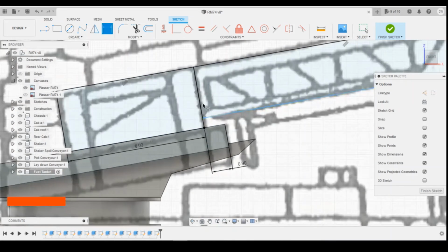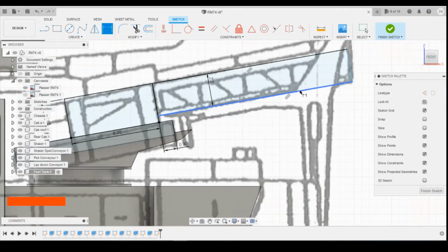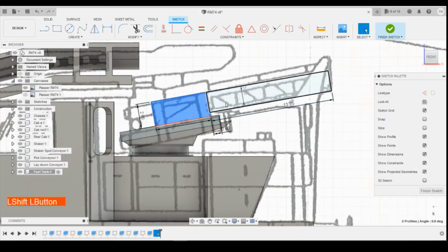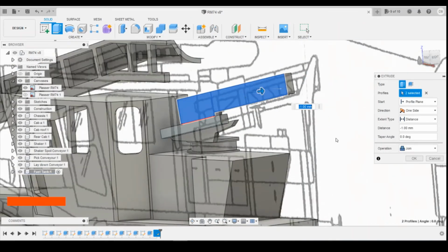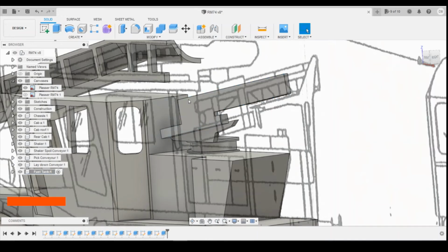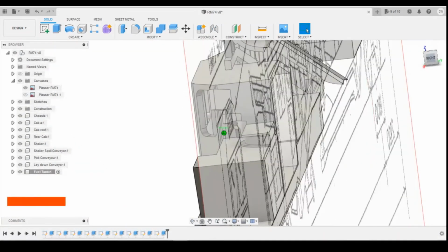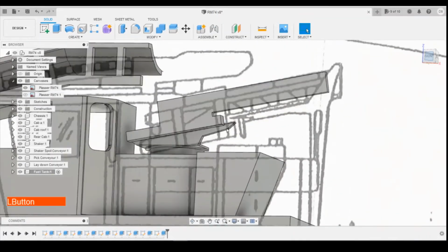Drag that back down. Inside, 2.2. Height should already be defined because it's locked into position at the top corner. Length 13.25. Let's extrude these back into the model by 0.5, I think. Again, I'm just looking at thicknesses that will give us strength on the model here.